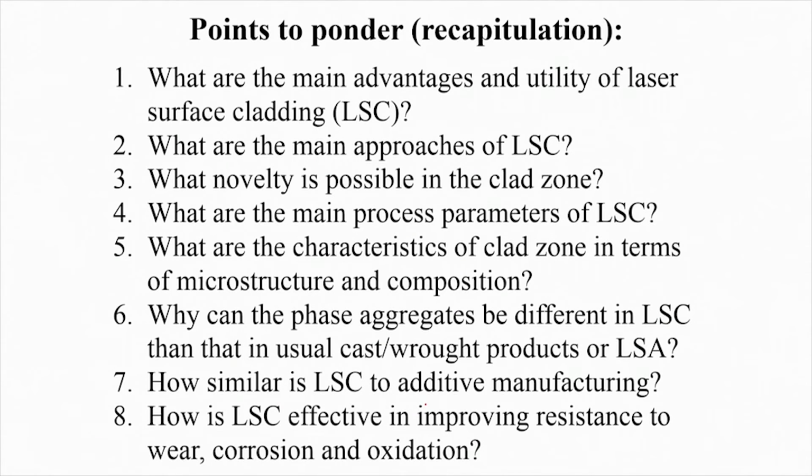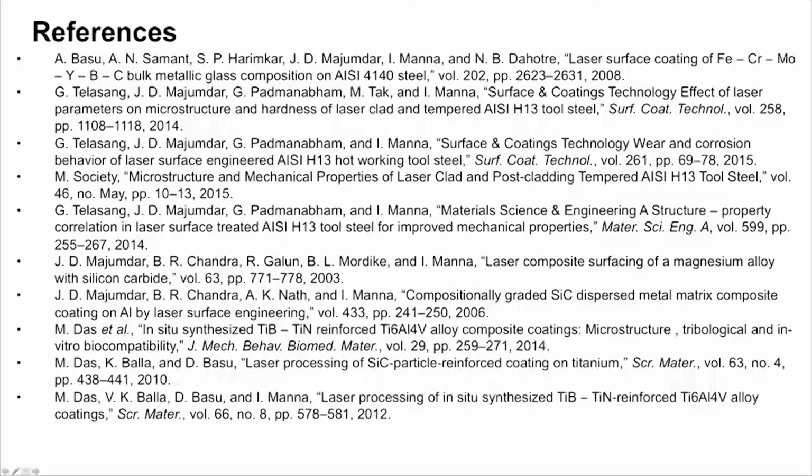The advantage here is that the fusion zone integrates well, so the mechanical properties or adhesion properties are much better. So because of the layer that we create, which could be much harder or much more corrosion resistant, we certainly can make a very significant improvement in terms of resistance to wear, corrosion, or any other surface dependent properties. So with this, we actually come to the end of the laser assisted surface engineering processes, and in fact also a discussion on all kinds of surface engineering techniques.